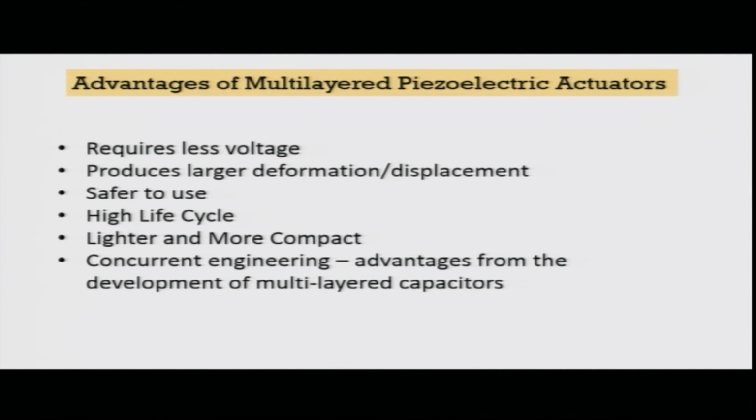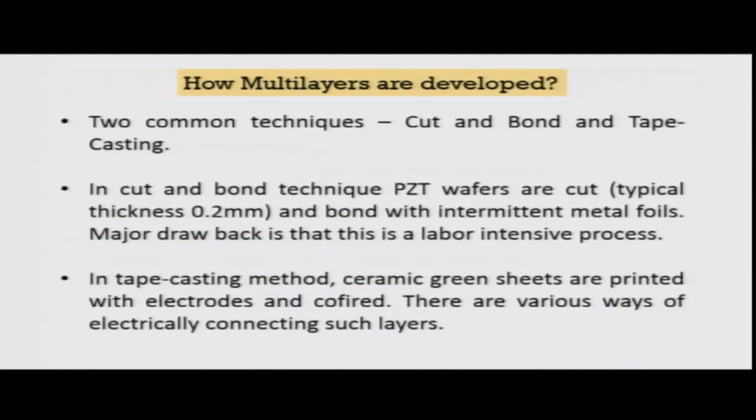Now, what are the advantages of these multi-layered piezoelectric actuators? Well, they require less voltage, produce larger deformation or displacement, are safer to use, have a high life cycle, and are lighter and more compact. It is also concurrent engineering, because you are thinking of it from the mechanical standpoint and also from the electrical standpoint, and it is a fascinating product of these two concurrent technologies.